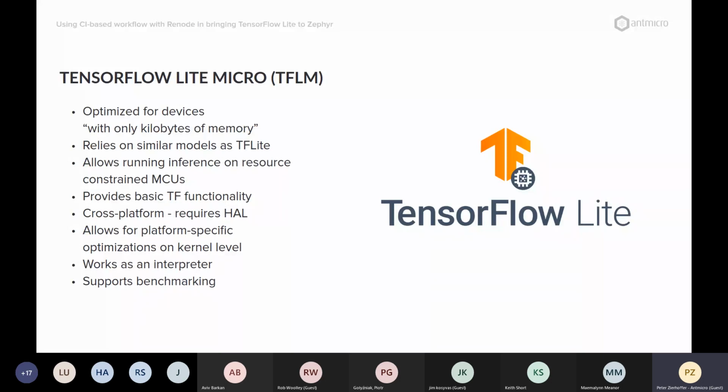Interpreters are not very popular in the MCU areas, but of course we have interpreters in this space as well, for example, MicroPython, right? But it turns out that this interpreter approach is quite clever because your neural network does not have to be compiled with your application. You can load it and possibly upload it over the air, so you can update it in the lifetime of your device, which is pretty nice.